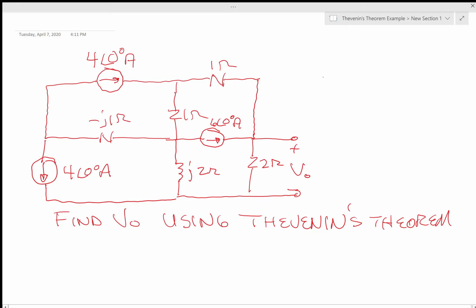Superposition is a little weird, but this problem, or a problem like it, is a really nice problem they put on the FE exam. If you use superposition, it is so easy because it's like 4 or 5 current sources, and each current source has a series resistor with it, and then they all go into parallel, and then there's like 2 resistors down on the end.